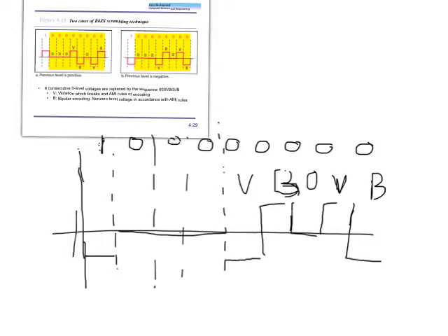Okay? So the receiver will recognize this as scrambling, and then it will replace all the 8 bits with zeros. So during transmission, I actually enhanced the quality of transmission. How? Because the DC component is not there, which is an inherent feature in AMI, which is good. The only problem here is synchronization. So by doing this change of voltage, I was able to enhance the synchronization.